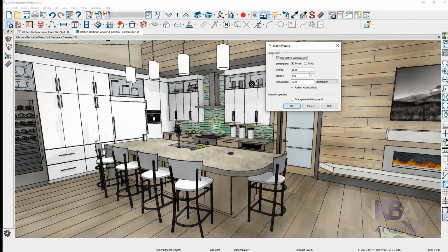You'll notice that my default window size is coming in here because it's cropped down after the title bars on the top, bottom, and sides. The height at most is 848. If you want a higher resolution image, at a minimum I will put in 1080, and that will create a larger image. You can always resize those down. It might be a little higher quality depending on what you're going to do. But make sure it looks good on your screen first, and then when you do the export, push it out at a high enough resolution that it meets your end target.